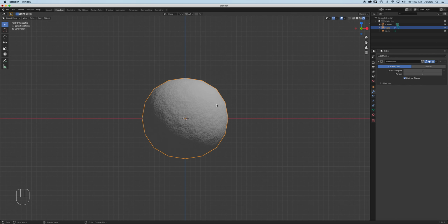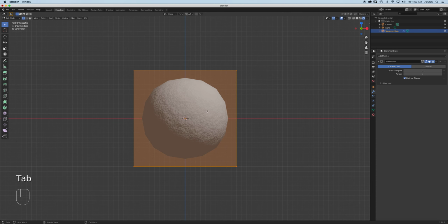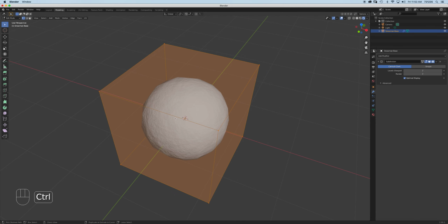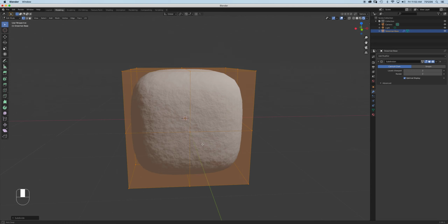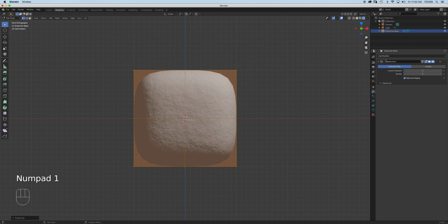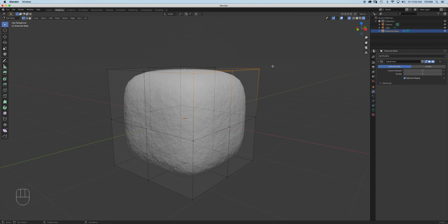All right, so this is going to be the base. So let's start giving it a name right here. This is Snowman Base. Okay, I'm going to hit tab, and then I'm going to subdivide this. So I can right click and subdivide. It just gives it loop cut, vertical, horizontal, and height. Okay, so if I go back to 1 here, I do want to turn on my X-ray. When you have X-ray on, it selects the components, the vertex right here, all the way to the back, so you're not missing anything.